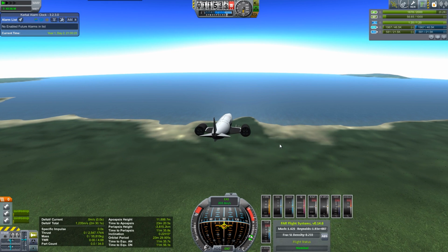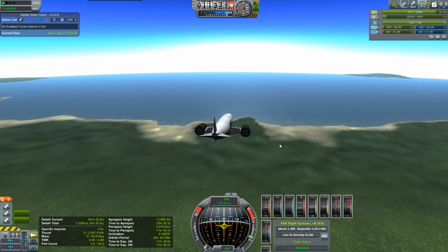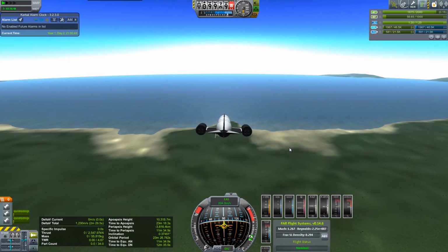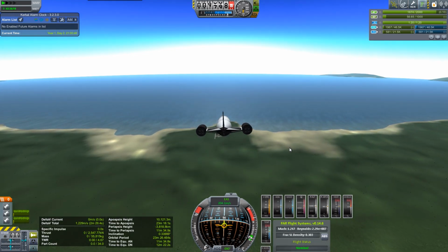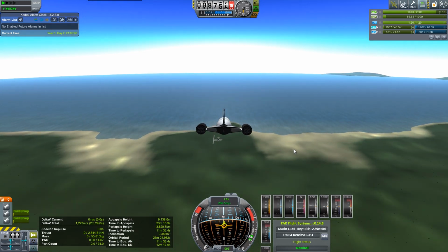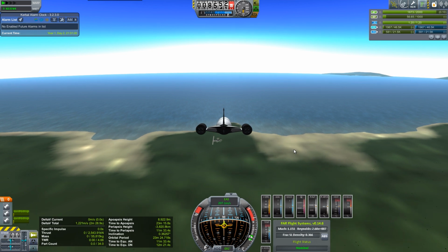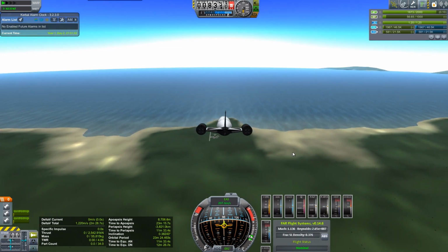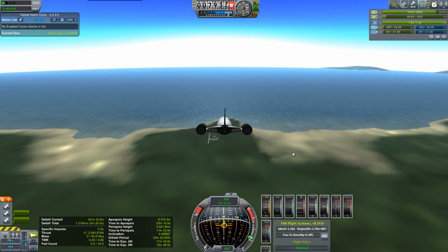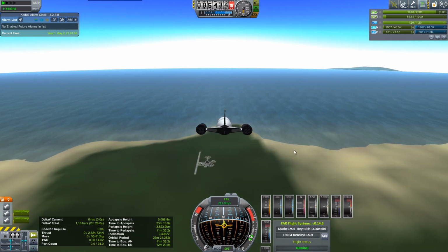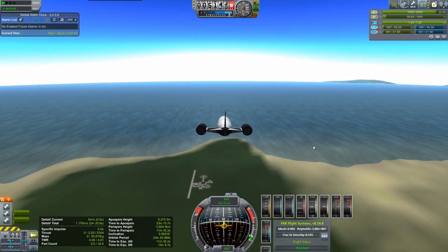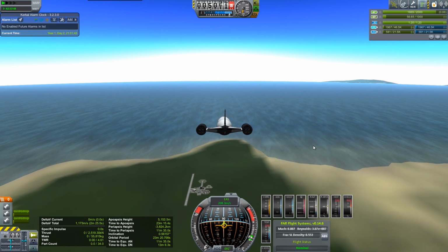Pretty soon we're going to hit Mach 1.2, and I need to pay particular attention to the pitch control as things will start getting strange. Yeah, there, see, it's trying to pitch up, so we'll trim forward some as we're approaching Mach 1.2. But the vehicle is very stable flying through the transonic region. A whole lot better than a lot of the things that I've designed. It's almost like, you know, real engineers designed this one. Back just a little bit to kind of level out a little bit. Or not quite level out, but just not drop as